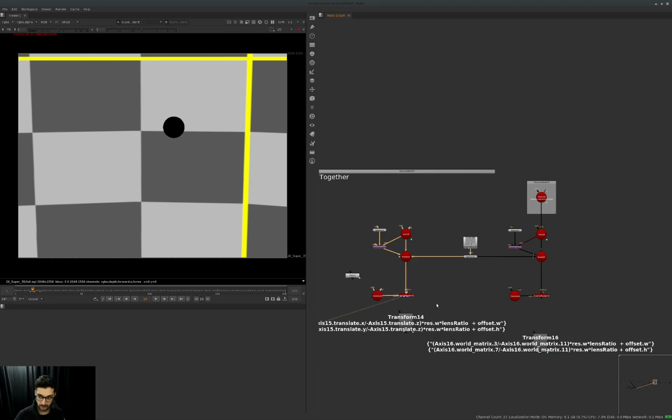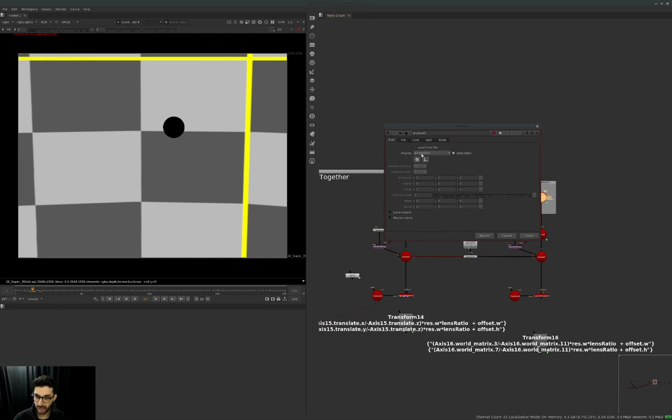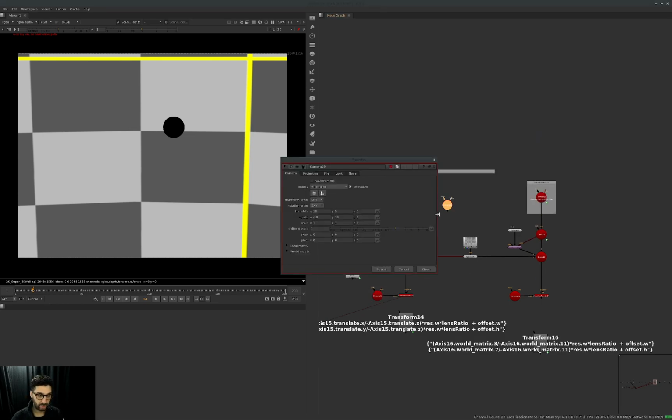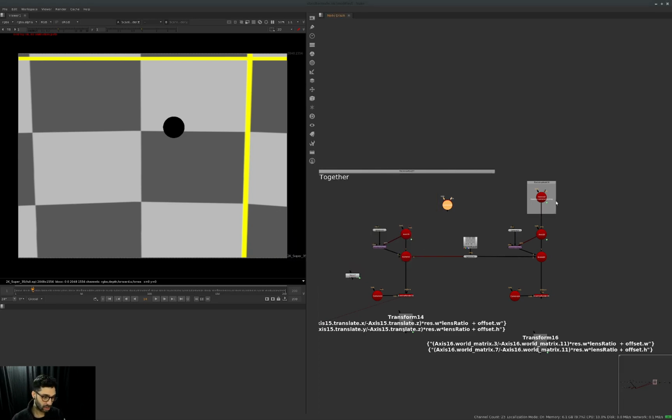Yeah, so I didn't do it. No, my tool is actually doing inverse of axis. Actually, there is an equation inside. But yes, if you want to convert that, if you want to basically swap it, then one way to do it without any tools is to go and do minus over here on all of them. So basically flip the sign and then flip the order. So if it's ZXY, do YXZ, and that should also give you the inverse animation, and then you can plug it in.